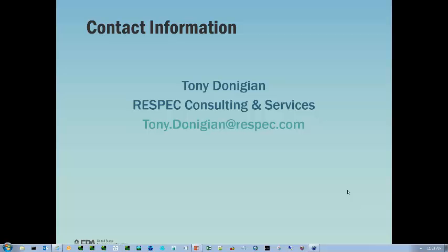It's an interactive program. It's an offshoot of the expert system that was developed for HSPF a number of years ago, and we call it EXP Plus or HSPEXP Plus. That's available to basically help post-process model results, because so many of these are written to either DBF files or the database files, WDM files, and you need programs to extract it from there, and we've pulled that together into a program to help extract that. Otherwise, you can actually just have the model output a data file from the WDM file, but you'd be running the model to do that.